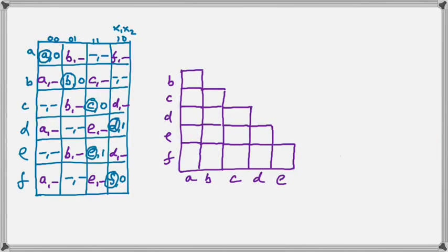Okay, now we're ready to take our primitive flow table and put it onto an implication table to find out how we may reduce or combine the rows. And once we do this, we will find that some rows completely go and others have dependencies. So for example, row AC would obviously depend on DF. But if we look at DF, we see that DF is a no-go. DF has an X in it.